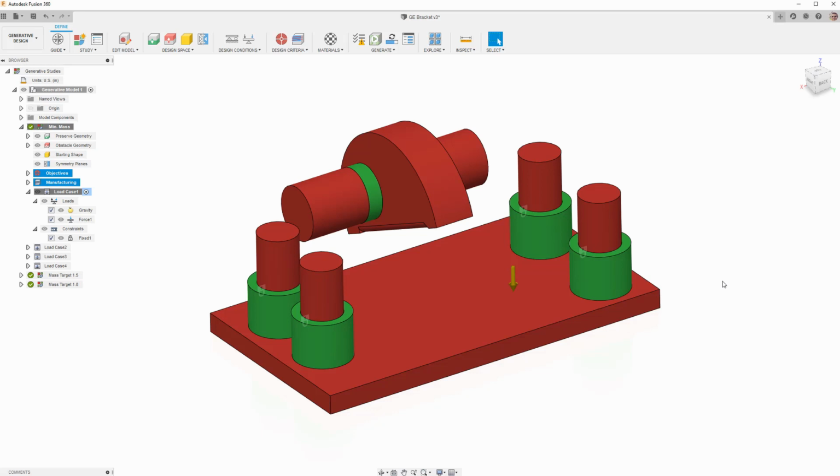So that's a loading scenario that I didn't often think of: installation loads and handling loads, before I'm able to actually fix a bracket to a wall or fix one component to another. So you just got to step back for a second and make sure you're taking into account all of those different loading scenarios.